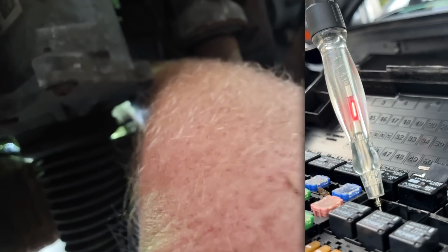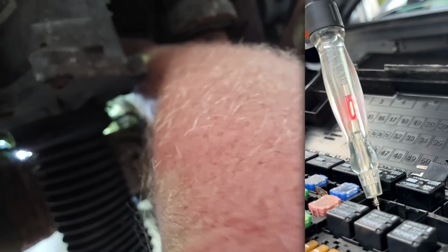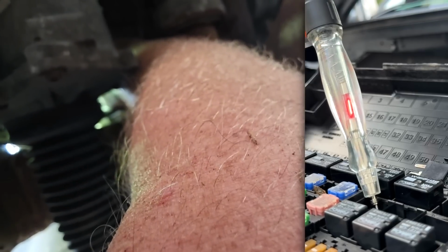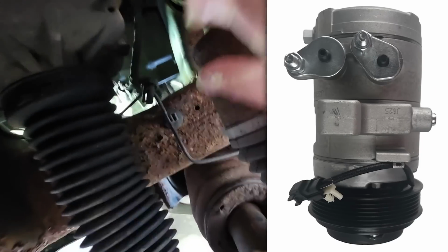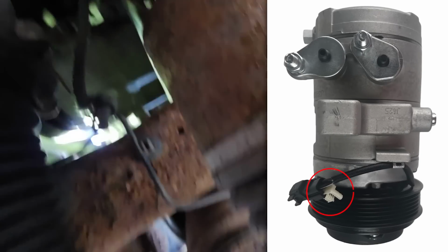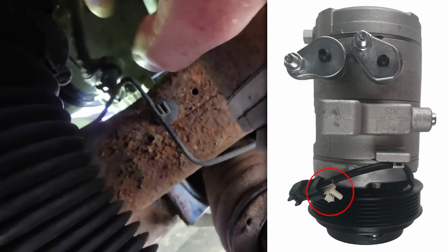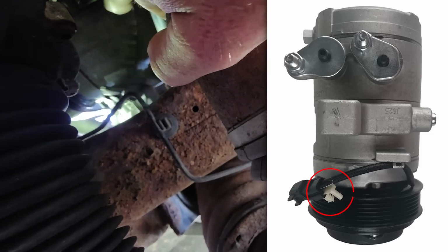There's a connector right here. Off, flickering. If I do that, what's it at? It's on right now. And if I do that, what's it at? It flickers. So I'm grabbing, I can't show you guys this. It's on the connector itself. This piece is loose, right? It's absolutely flickering. Yeah, and I believe our problem is right in this connector.